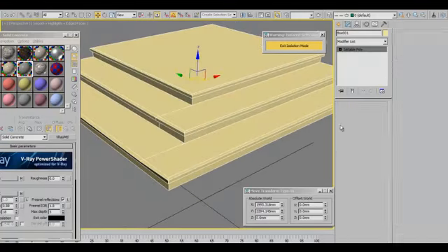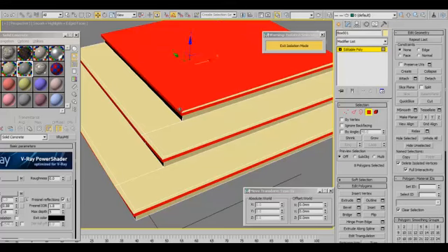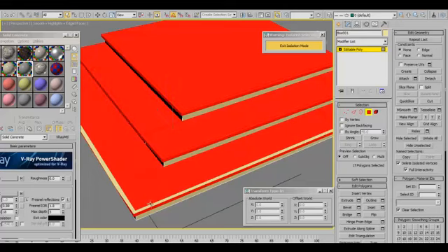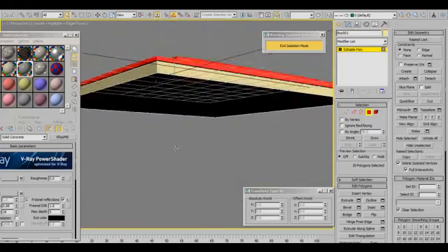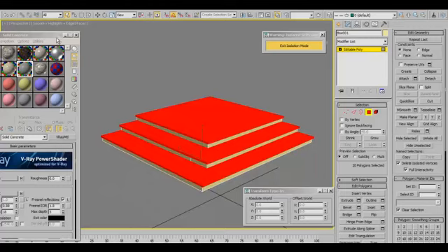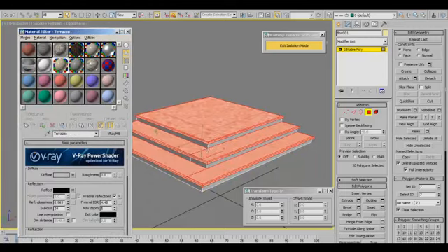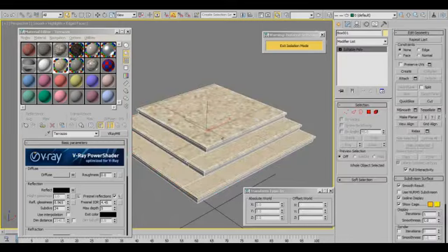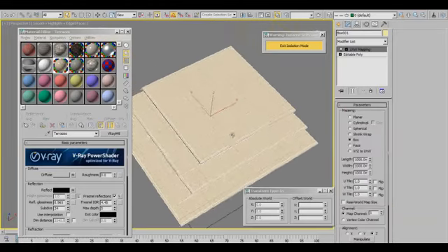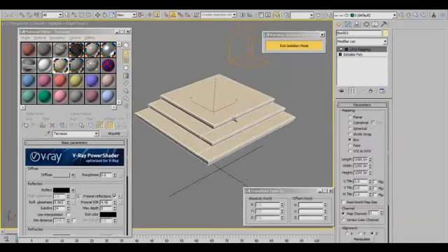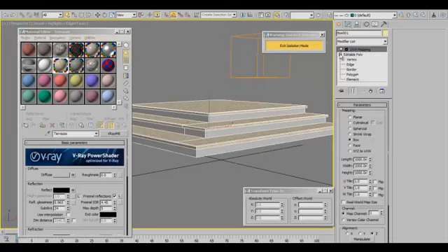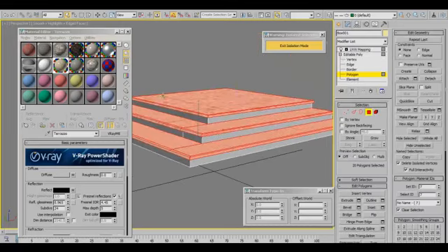And okay, to apply that, we just select the top faces because we need to apply the terrazzo material over this area, and I think we've got that selected. Then we can pick our terrazzo and apply. Then of course we would have to put the UVW map because you can see how chaotic it is without a UVW map. So we can just paste the previous one too, and you can apply a new one if you need to change the setting, and you can paste it and equally just adjust from here. And we're going to apply the concrete material to the other part.